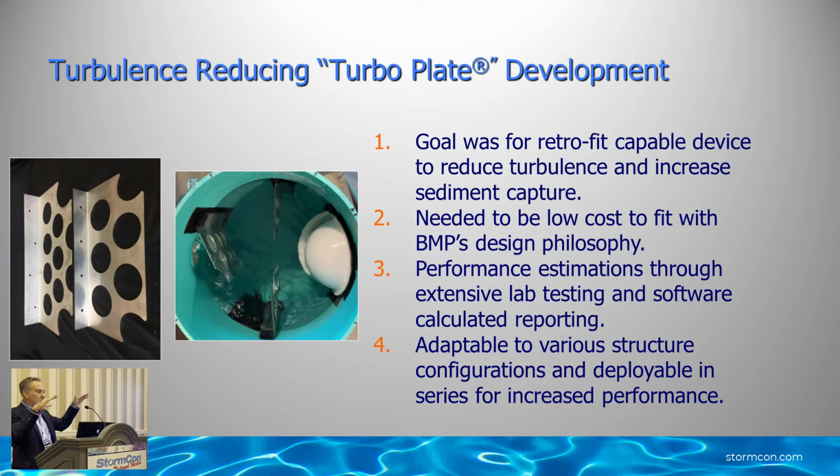We get things in layers, we reduce the turbulence, and we allow gravity then to impact these particles in a way that we want to control. And that's what stormwater quality is all about, right? It's controlling the environment and targeting the pollutants that we want to get rid of, and using some hydraulic tricks to put them in a place that we can deal with them and take them away later. That's it. That's all water quality is. And the more tools you have to throw at that magic trick, the better it is. And so this is just that.